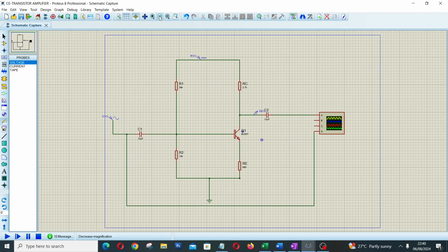That's why in amplifier design there is a procedure we normally call negative feedback. Negative feedback is a process through which we feed back a portion of the output of an amplifier to the input in order to control the gain, so that the gain will not be excessive. In this system, I want to quickly show you how you can find the frequency response curve. From the frequency response curve, you'll be able to see the range of frequencies where this amplifier can operate. So let's see how we do that.